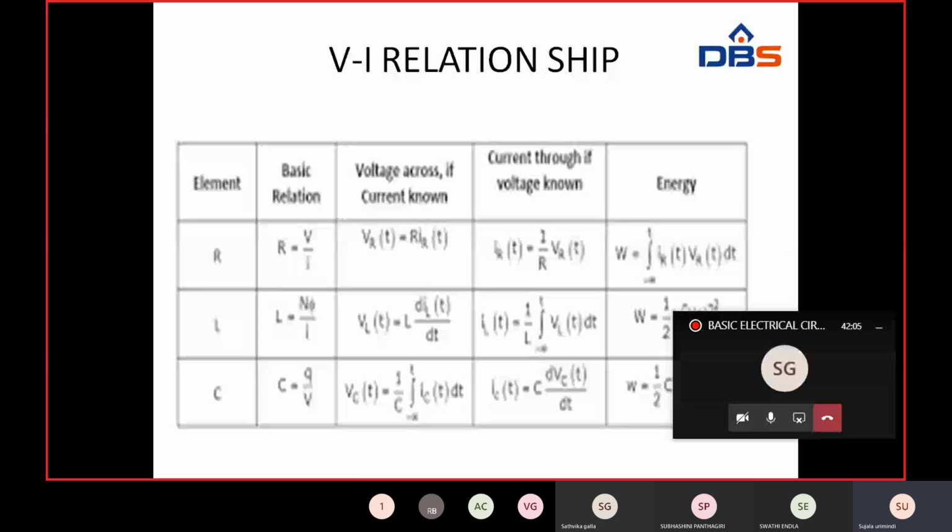Depending upon the polarities, when there is minus to plus, there is a rise of potential, put it as a positive sign. When there is a drop of potential, that means plus to minus, it is decreasing, then you put a negative sign. For the voltage sources, we need not change the polarities, but for the resistors we have to change the polarities depending upon the direction.